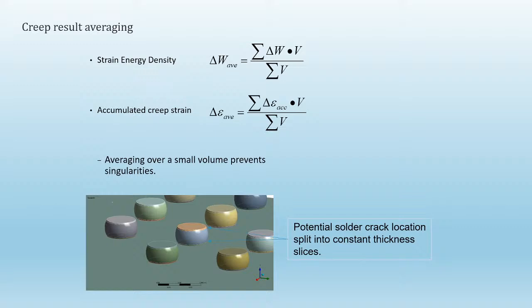I see a couple of questions came in. Can the same methodology be used for surface-mounted devices like QFN? Yeah, definitely. BGAs and QFNs are very similar in the way that they're attached to the PCB. They both use a sort of surface-mounted technology. With QFNs, you would have a thinner layer of solder, but you can use exactly the same methodology.